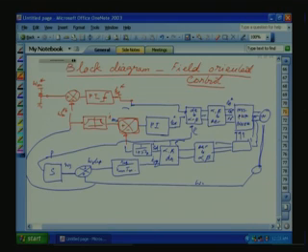But as I told, the problem with the hysteresis control previously is its wide switching frequency variation, and optimum PWM switching is not required. So, if you use a voltage controlled converter with a space vector PWM or sine triangle PWM, then the reference to the PWM is not current, but voltage. Then the field oriented control scheme, the block diagram, will be like this.